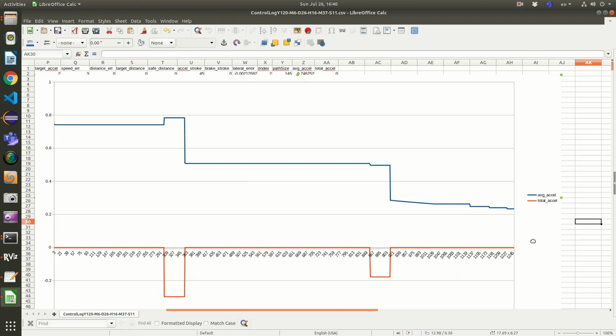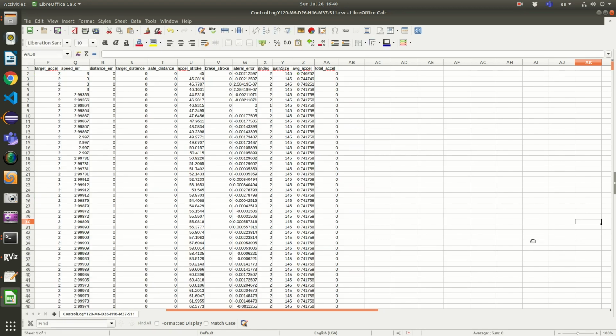This could be useful when we calibrate, or even in the common parameters of OpenPlanner, there is a variable we can set which says what our maximum deceleration and acceleration are. We can use this to handle the threshold for our target velocity better than just assuming a value.